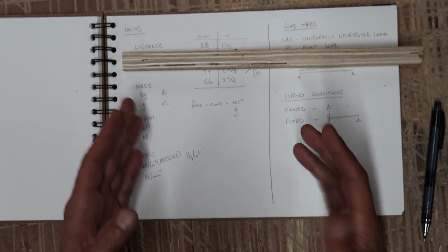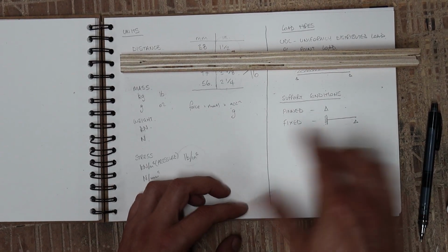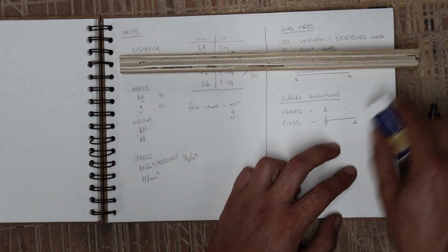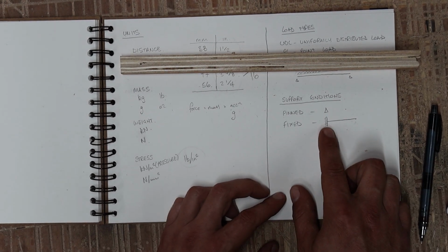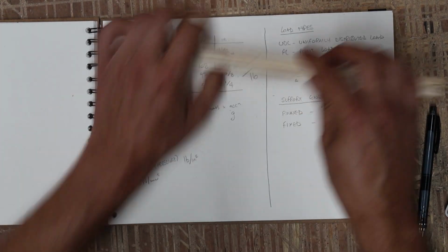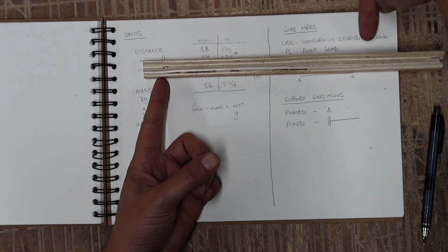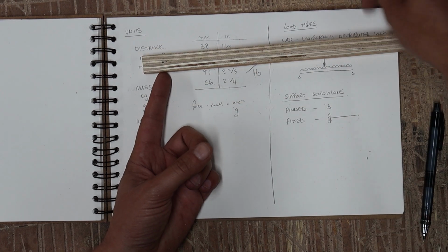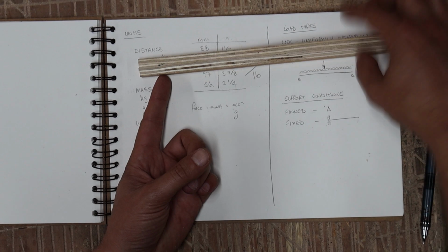So when we have a system that moves, it's bad. Let's just imagine moving buildings. No one likes moving buildings. Let's imagine this cantilever situation again. What about the support? Let's imagine that we didn't put a fixed support condition at the end, and we just supported it with our finger. Gravity's still acting down. When I push down, it would just move freely. There's nothing there to stop it. That is a mechanism. That's an out of balance load.